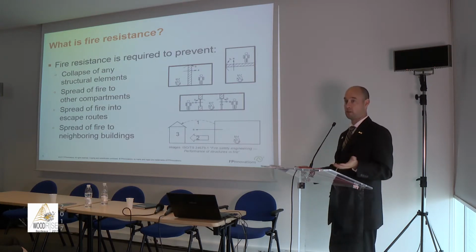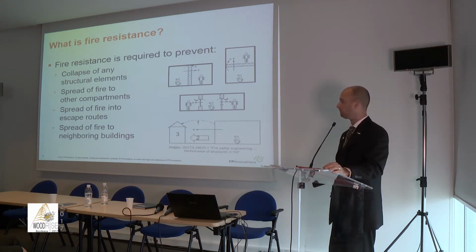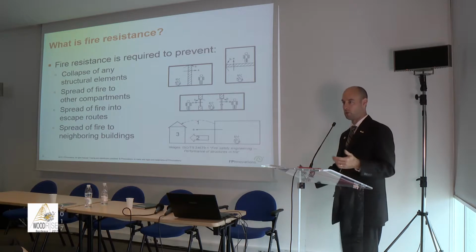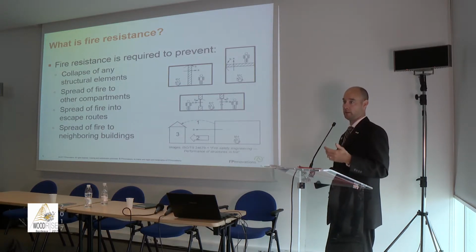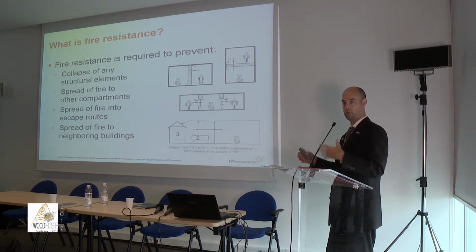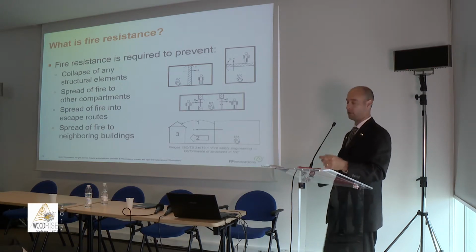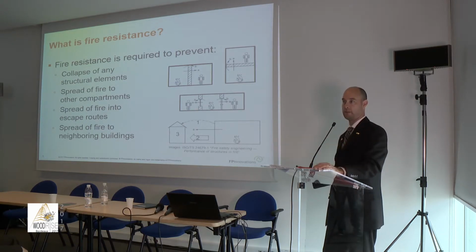Basically, fire resistance applies, of course, to the load-bearing elements, so posts, beams, and walls. But it is also used to prevent fire from spreading beyond the compartments, so it has to be kept confined within the compartments. It could be the walls, the floors, but also the windows, so the glazing, the fire doors, different assemblies that need to maintain a fire from going outside. And there's also the effect of fire spreading to neighboring buildings.